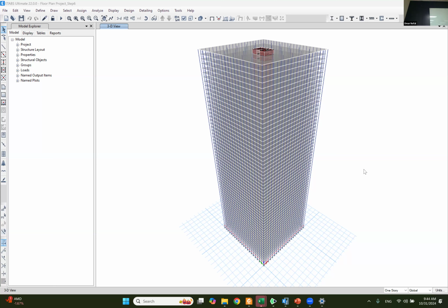So it's like design for dead load or live load. The main thing for designing for dead or live load, we need to know how much load the beam or the slab is going to have, and then do analysis and get the internal forces: normal, shear, and bending moment. Same thing with earthquake. We need to have the loading. The loading is not direct, like dead load or live load where we have on the flooring 200 kilograms per meter square or something. It's not direct like this. It's a function of time, something that keeps changing over time. So we need to see how this time-changing load is going to impact our building.